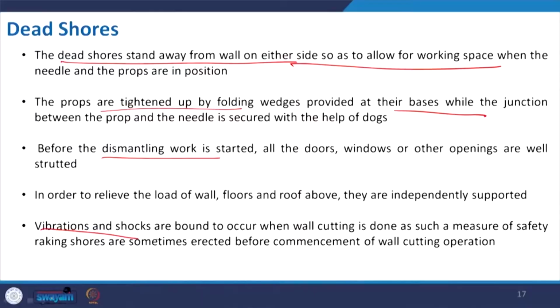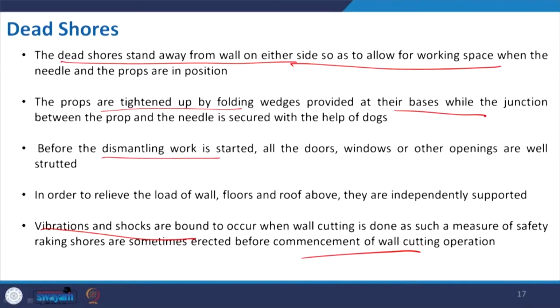Another important and very vital thing in this is vibration. During the work, when you go for reworking or rebuilding, there will be lots of vibration, and that will impact the temporary structure. So, we have to take care of that, and properly tie all those components together, so that it can resist those vibrations during the reconstruction or cutting any portion of the bearing wall.